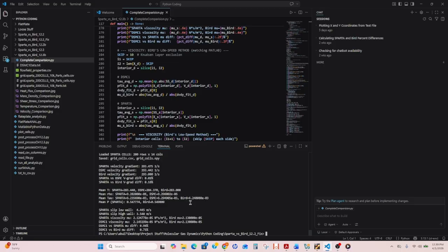So that just lets you know exactly how low the density actually is if the pressure is only half a Pascal compared to what we have here at the surface of Earth. Start looking at the slip on the walls. The main thing that we were looking at for this project was the viscosity coefficient. And you can see that here's my SPARTA viscosity coefficient, and then here's what Bird reported his was. This is all really close to what the measured value was that Bird was comparing to.